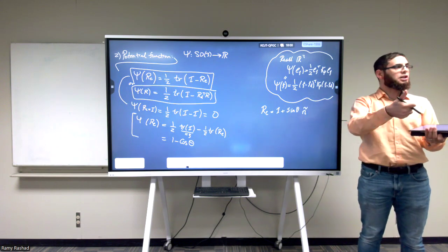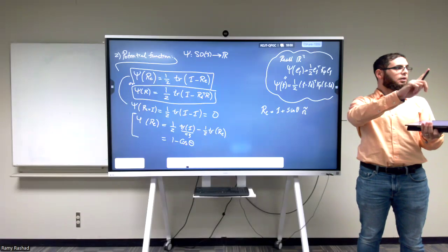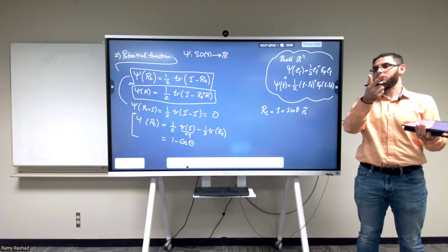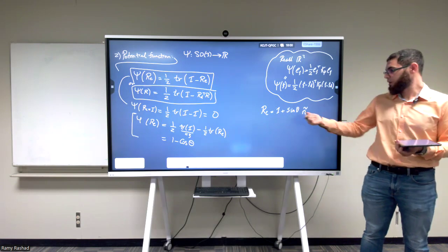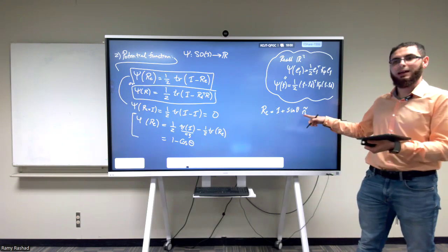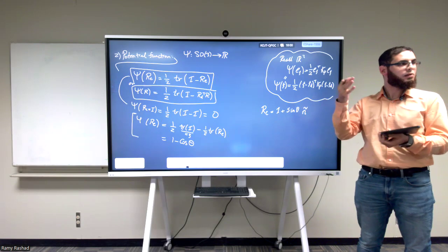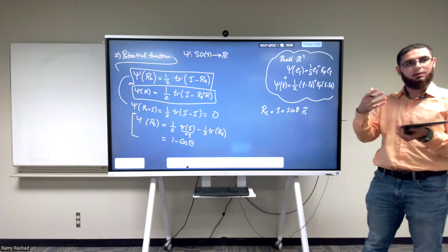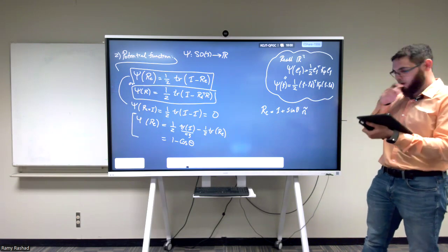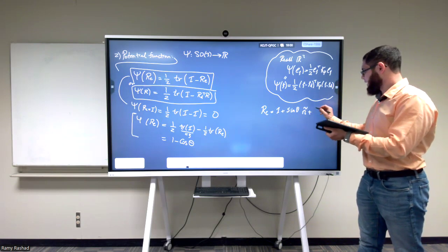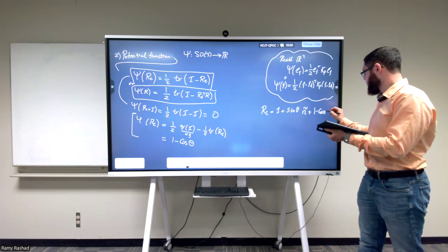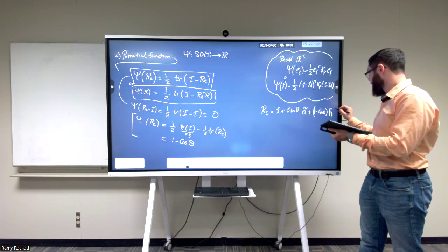So we can always write a rotation matrix locally as an angle and an axis. This is just a parameterization of the rotation matrix. This is a unit vector, and this is the angle. So we have these 3 numbers, these 3 degrees of freedom, that correspond to the rotation matrix. And the Rodrigues formula, if you remember it, was given by this expression.